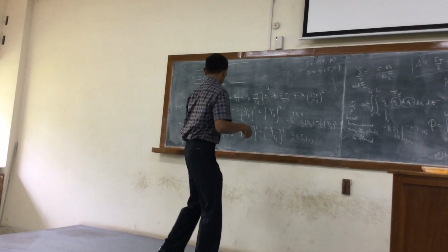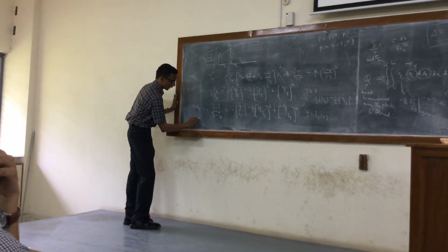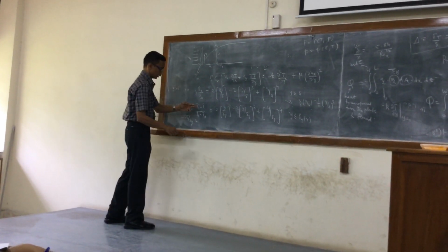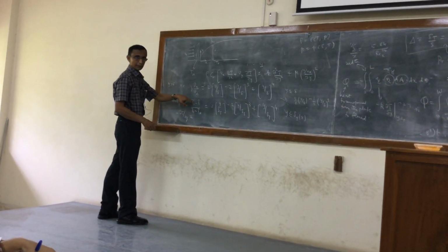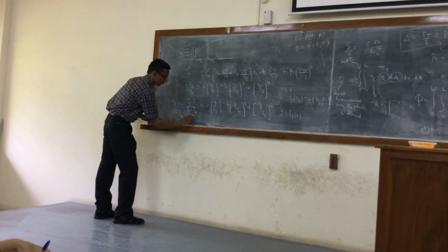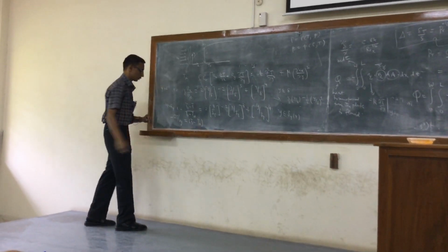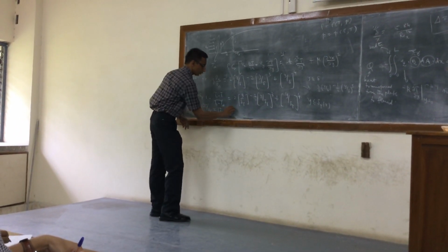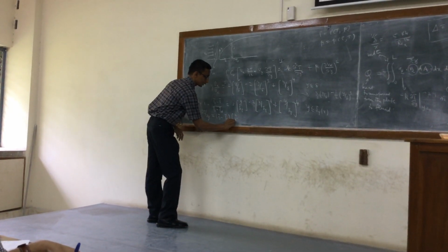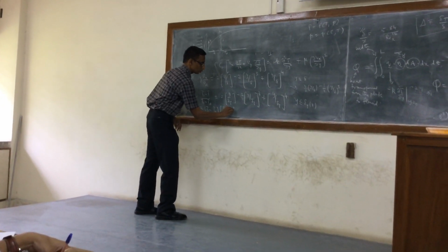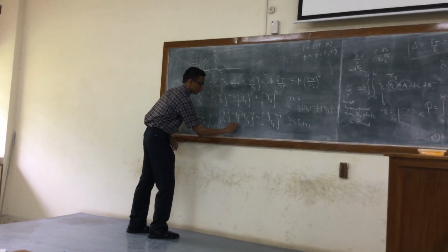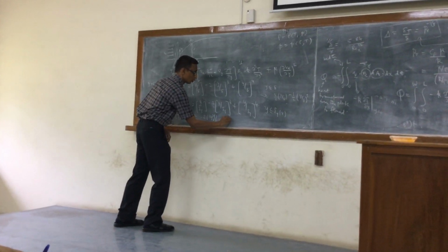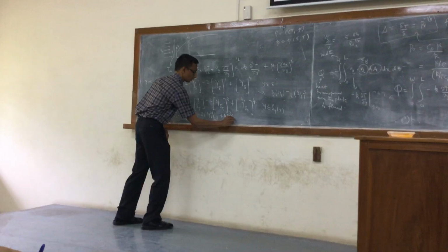So if I take this, so clearly minus dT by dy is equal to, right? So I have minus T, and the T0 minus T infinity, so I am going to take T0 minus T infinity to the other side. So I am differentiating then. So then that would have to be differentiated. So I get 2 over delta T, minus 2 times 3y squared by delta T cubed, and then plus 4y cubed by delta T to the fourth.